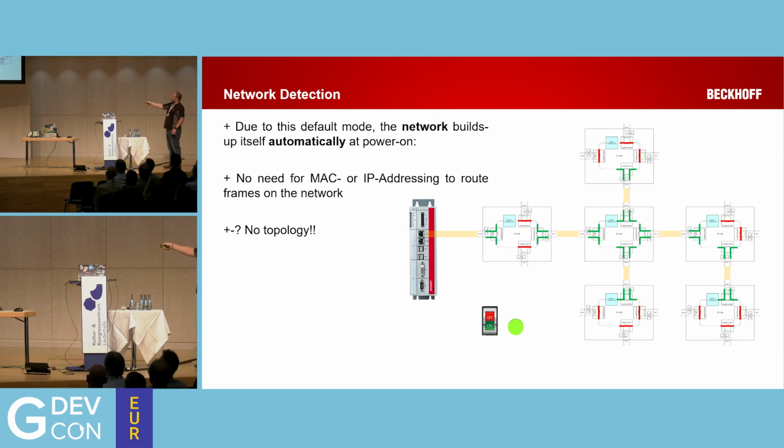The benefit of that is you don't have a lot of complex network setup. It doesn't matter how many devices you've got in your network, it will auto-detect and bring them all back to your EtherCAT master for you. You don't have to sit there and give IP addresses and identities to every single device in that system.